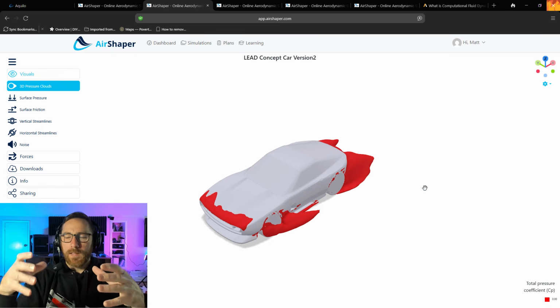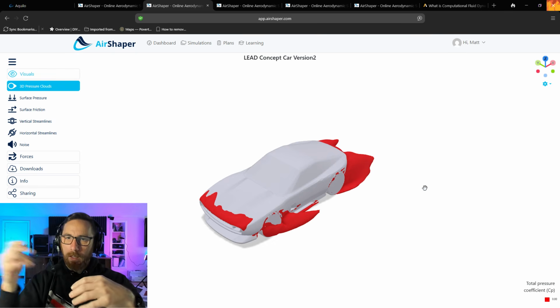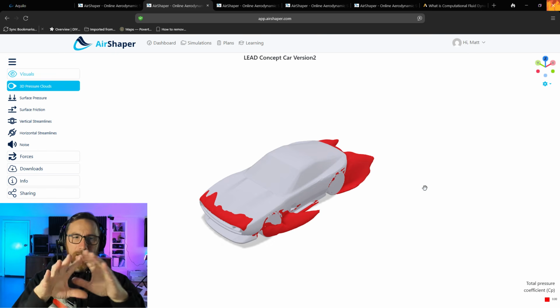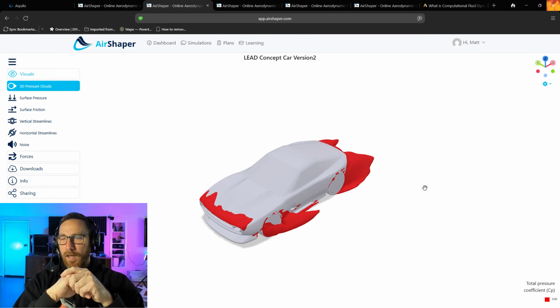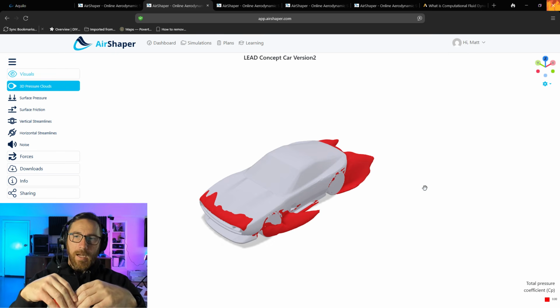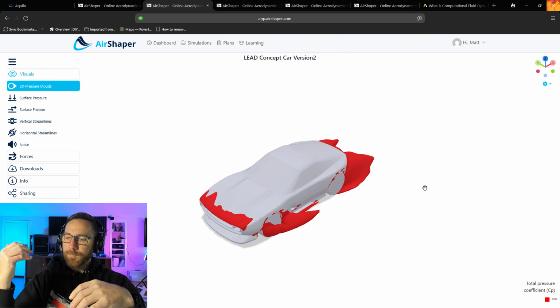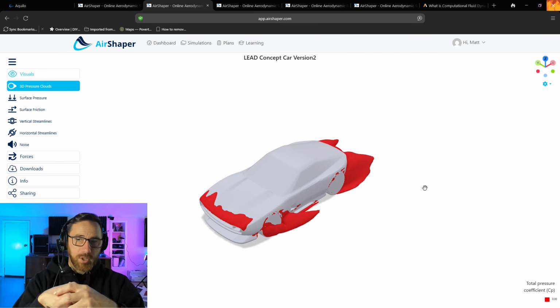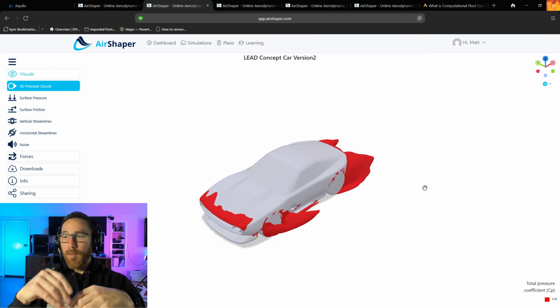So if you're doing, let's say, flow through a computer, like a CPU tower, and you've got all of this venting on the front, and you've got fans on the back and so on, this becomes a really complicated setup problem. And then if you've got models that are not all native CAD geometry, if you've got some mesh data, it won't work. In many cases, it has to be CAD geometry. Otherwise, it needs that to be able to mesh for itself.